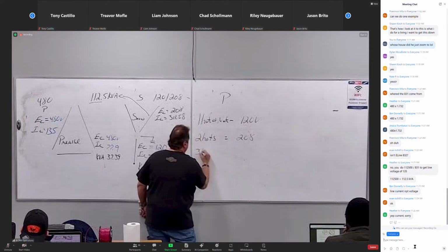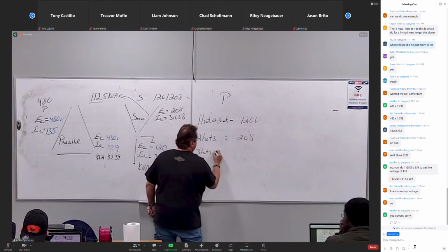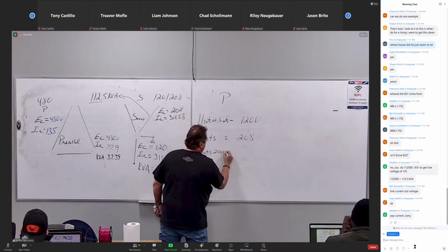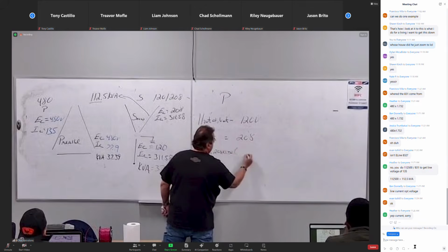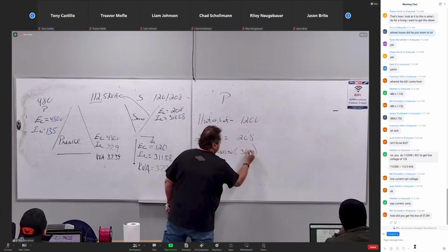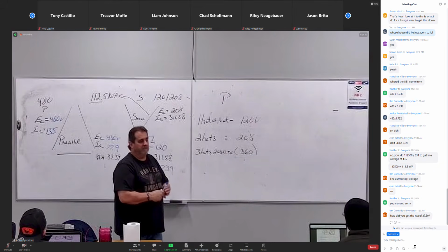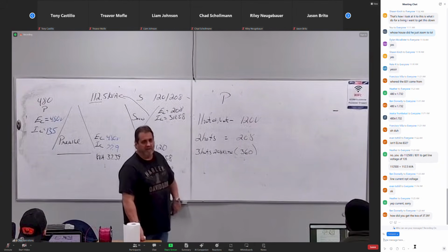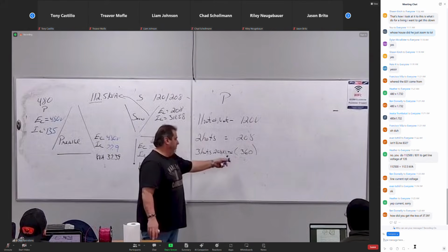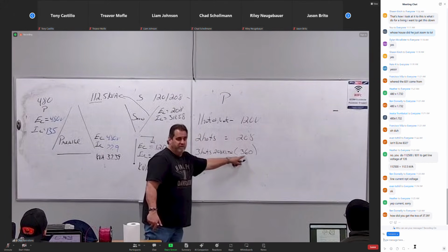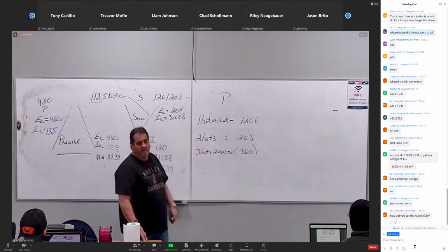But if I have three hots, I have to take the 208 times 1.732, otherwise known as 360. Well, we don't have a meter, so nobody recognizes 360. They're like, 360, where'd you get that from? What type of panel does it have to come out of? Well, you would have to divide it by 1.732 to figure out that you could come out of a 208 volt panel. Does that make sense?